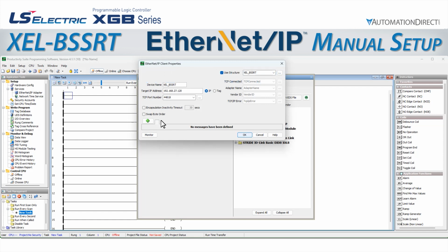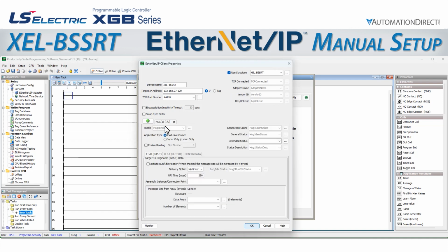Now let's add a message. We click the green plus symbol and we will add an I/O message. Some of the fields are pre-populated with structure tag names, but we want to add a tag in the extended status field. This is technically optional, but most of the troubleshooting for Ethernet IP connections in Productivity will be greatly improved by having this detailed information available. We will call our tag BSSRT_extended status.